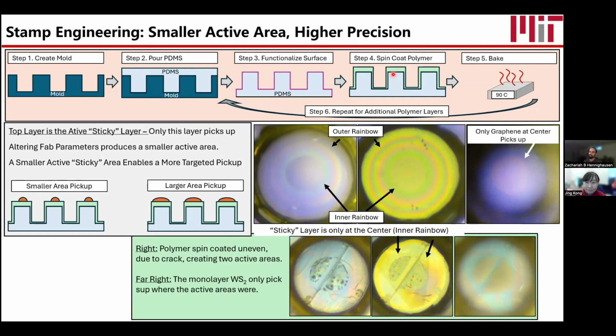We hydroxylate the SiO2. Shout out to my peeps over in Professor Nurui's group, who gave me the idea and helped me along with it. If you hydroxylate the surface, you make the SiO2 very sticky, and then the 2D material just wants to leave, and it pulls off the polymer. Then you rinse the polymer very quickly, and it seems to produce a clean surface, but we have to look into that more. So I'm trying to engineer different surfaces. Currently I drop off by functionalizing the SiO2 and making it very sticky, and then it pulls off. That's a very reliable method. Thank you very much.